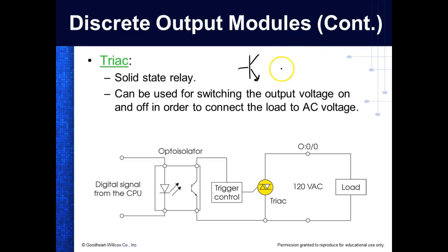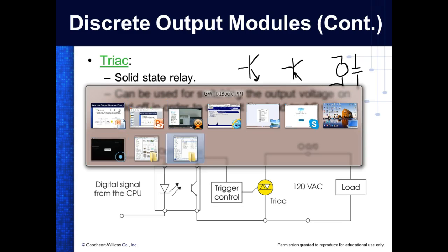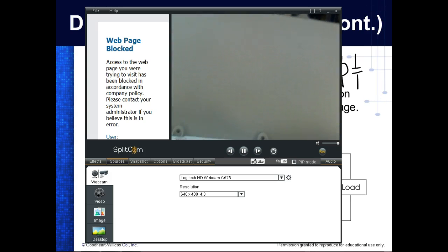You say they're going to use a PNP or an NPN transistor. And then a relay output, your module is going to control a coil, and then we're going to have a contact that you don't see. That's going to, what's nice about a relay is you can hook up what to it? AC or DC. So we established a common. So if we look at the Allen Bradley PLC, y'all can see this, guys. It has a relay output. And down here on my outputs, is it going to focus in on it?